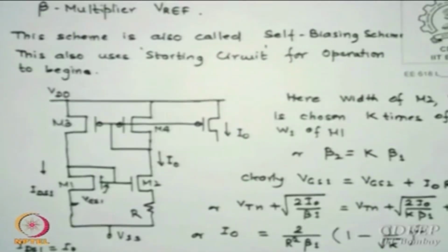So the thermal variations are immediately seen. In analog it is even worse, why? I's are higher than digital. So I square R is even stronger, so more temperature is likely to rise in analog parts than in digital. That is why we say look into how temperature constantly varies.